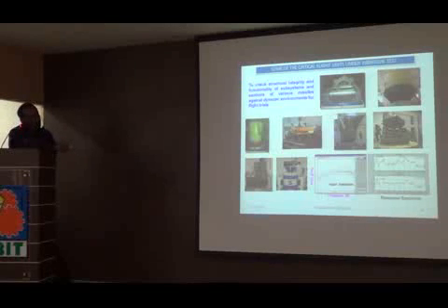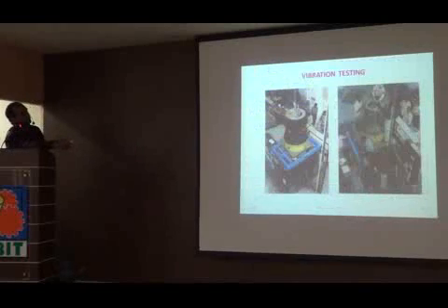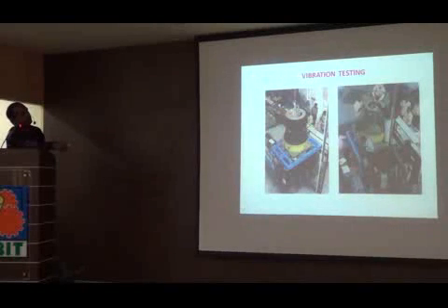By reading this response information, we will know where it is amplified, where it is fine, or whether it can withstand the vibration, and what the effects are, what the total acceleration input is at the corresponding packages. All this information we read from the responses, and if required we do some structural modification. I will show you some of the structural modifications we have done as a case study. You see, this is one of the Agni missiles when we test it, how it looks.